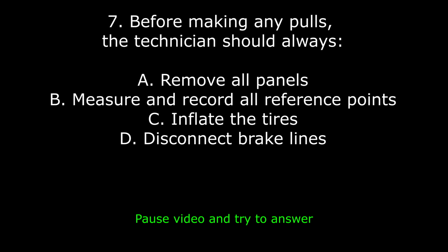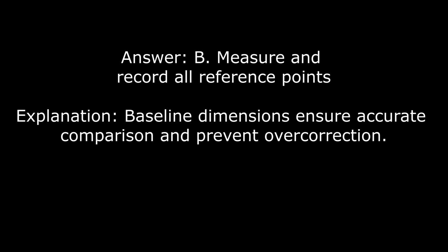7. Before making any pulls, the technician should always: A. Remove all panels. B. Measure and record all reference points. C. Inflate the tires. D. Disconnect brake lines. Answer: B. Measure and record all reference points. Explanation: baseline dimensions ensure accurate comparison and prevent overcorrection.